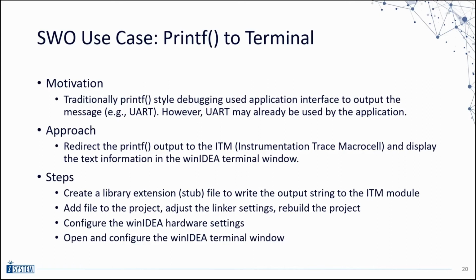One last time, we go back to the presentation to discuss the use case printf to terminal. The aim of this use case is to redirect the printf output to ITM and display the text information in winIDEA. Traditionally, printf-style debugging uses a user interface, for example UART. But there is a possibility that UART has already been used. So instead of UART, we can use ITM to redirect the messages.